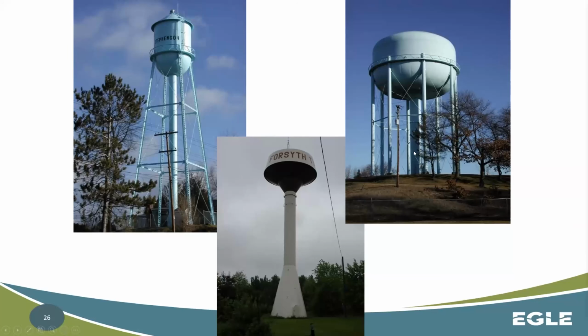So it's a large diameter wet riser. It's very large piping that runs up. This is actually not an insulated portion here, but because so much volume of water is moving, there's not typically concerns for freezing. On the other side was a more narrow pipe that runs up, and they were having issues with freezing. So this was originally a wet riser and was later converted to an insulated dry riser. This exterior portion, what you can see right here, has a pipe that runs up the middle of it. That's now insulated from the direct weather conditions, so they're not having those same issues with freezing.